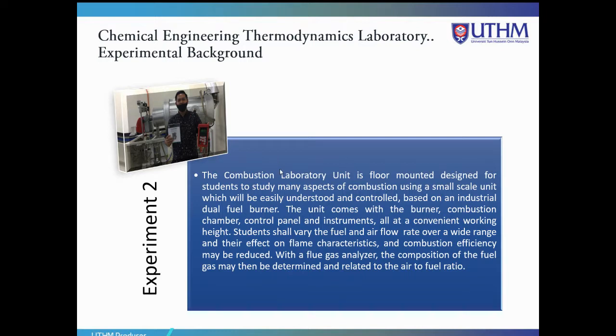With a flue gas analyzer, the composition of the flue gas may then be determined and related to the air to fuel ratio. So basically, for this experiment too, the objectives are as listed: to determine the type of flame at different air to fuel ratio. The second objective is to determine the product of combustion at optimum air to fuel ratio. And the last objective is to determine the heat transfer balance for water in and out.